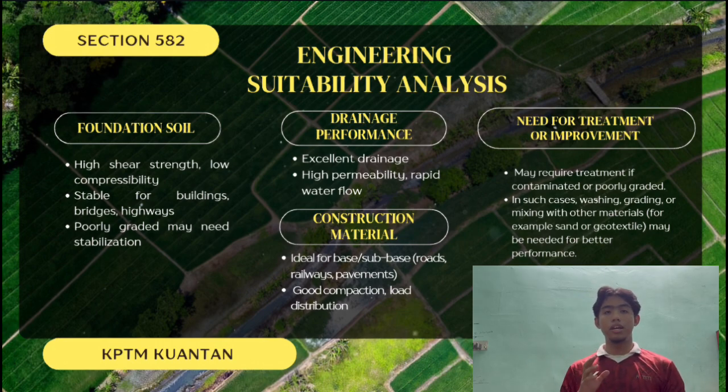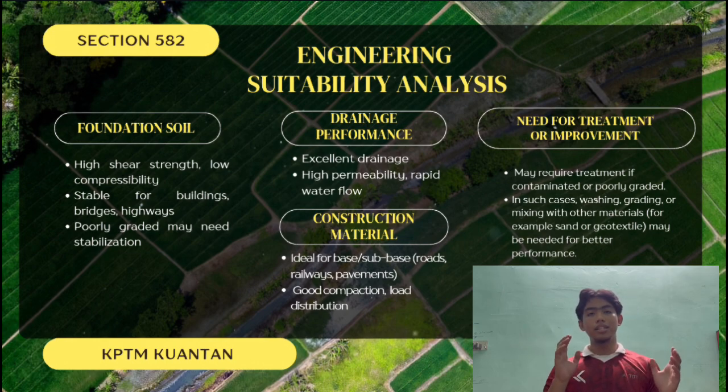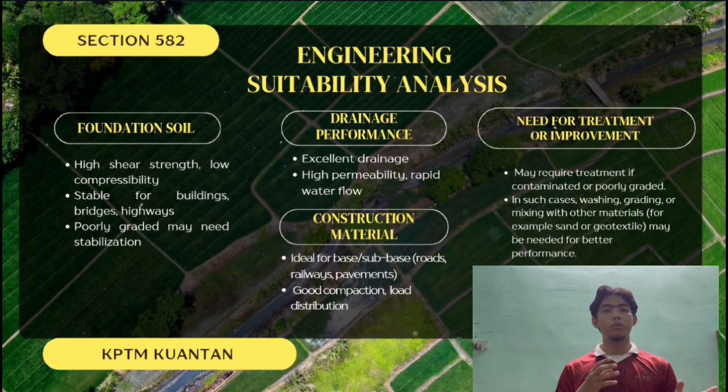Gravel has high shear strength and low compressibility. If the gravel is well graded, it becomes very stable for buildings, bridges, or highways. If the gravel is poorly graded, it may need stabilization.